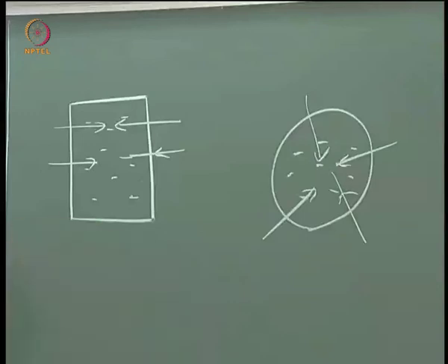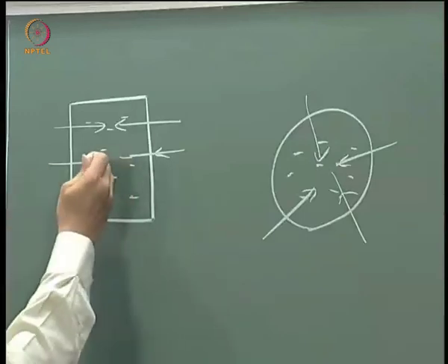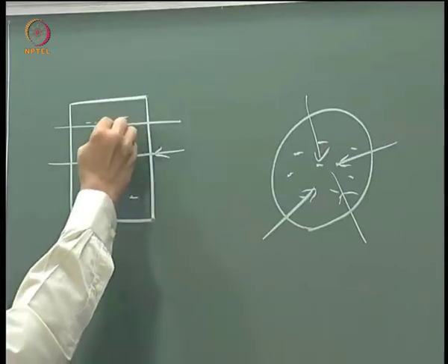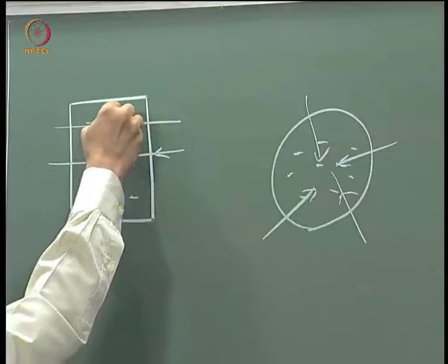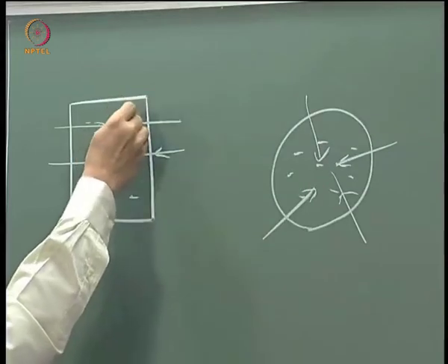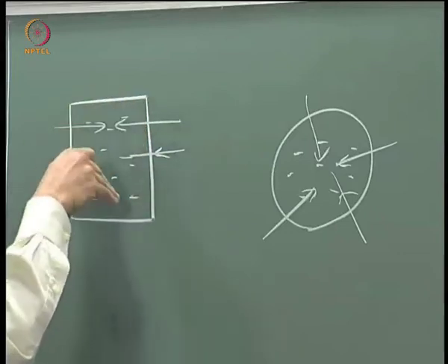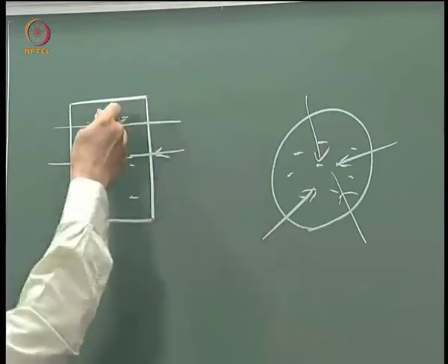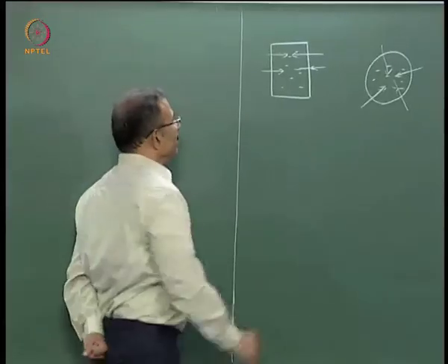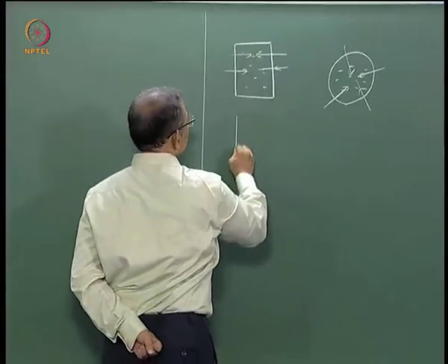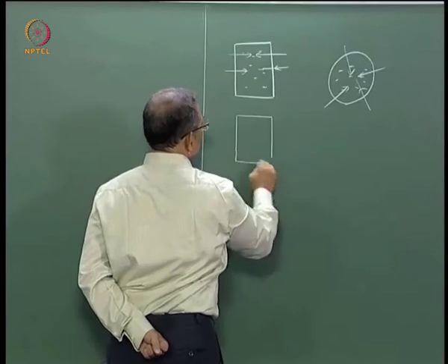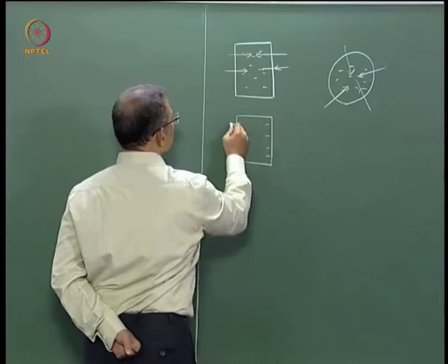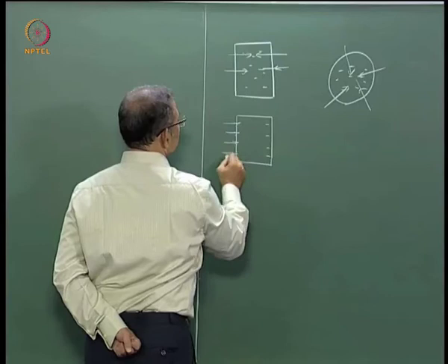So, we will look at our one dimensional situation. Now, what is the consequence of this electric field coming here and terminating on the charge? Now, since this charge that we have injected is mobile, it will move in this direction, right. So, the electric field that has been created as a consequence of the space charge itself will try to drive the electrons either to this side or to this side. Now, this is the reason why ultimately the process stops only when the electrons move to the surface, because thereafter the picture would be something like this.